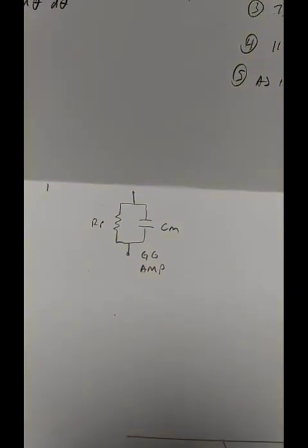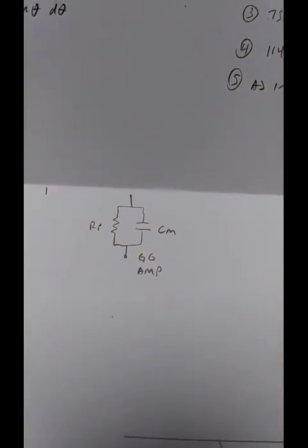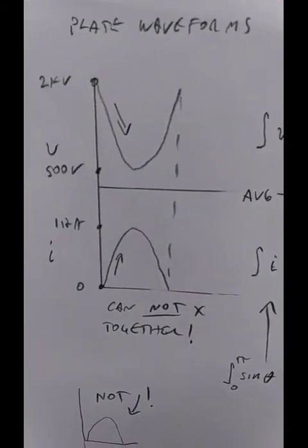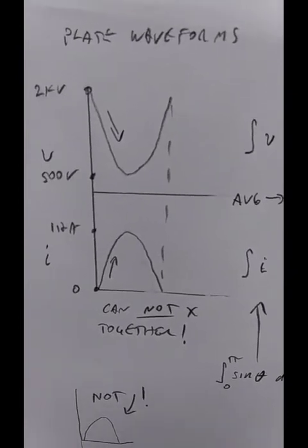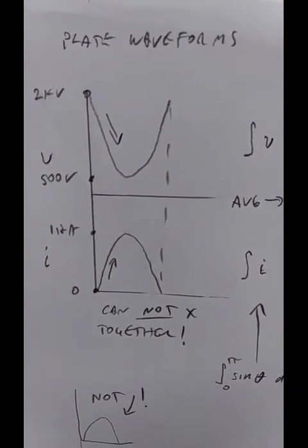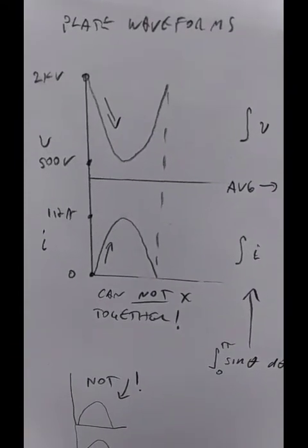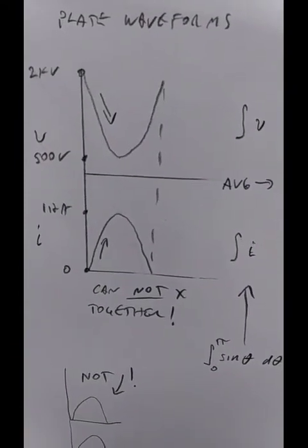As frequency goes up, that Miller capacitive reactance goes down, and it starts doing weird things with the phase. It'll throw the voltage and current out of phase and induce a reactive component, and recall from basic electricity, reactive power is not real. It's VAR, volt-amperes reactive, not dissipative.